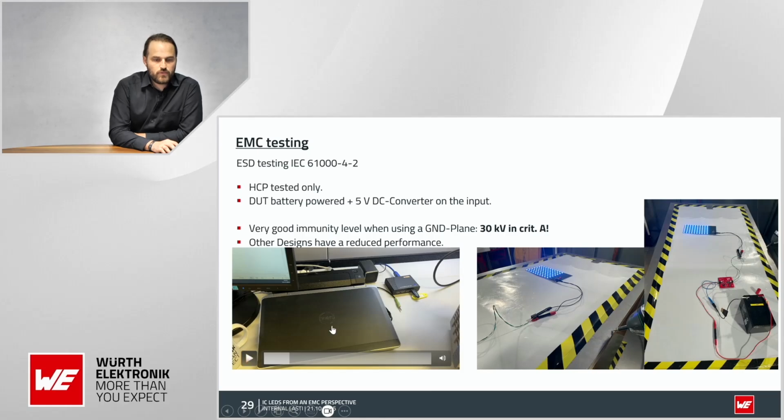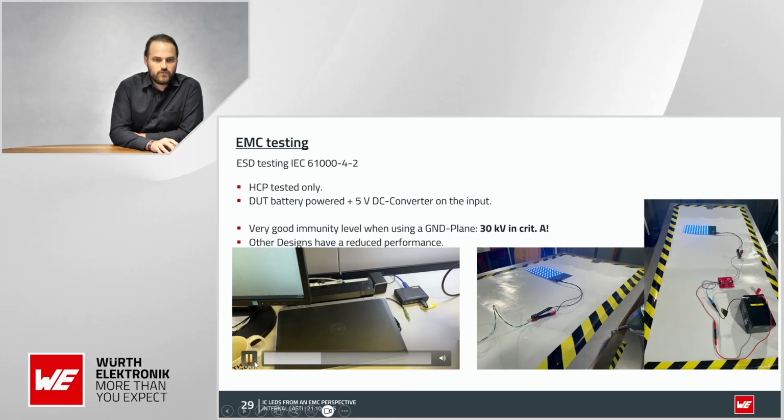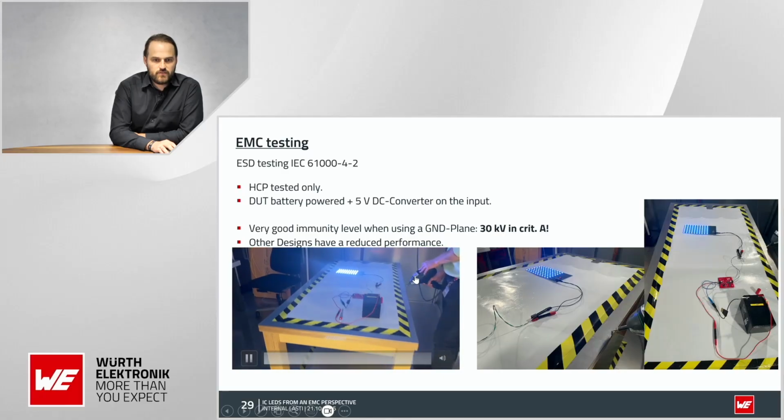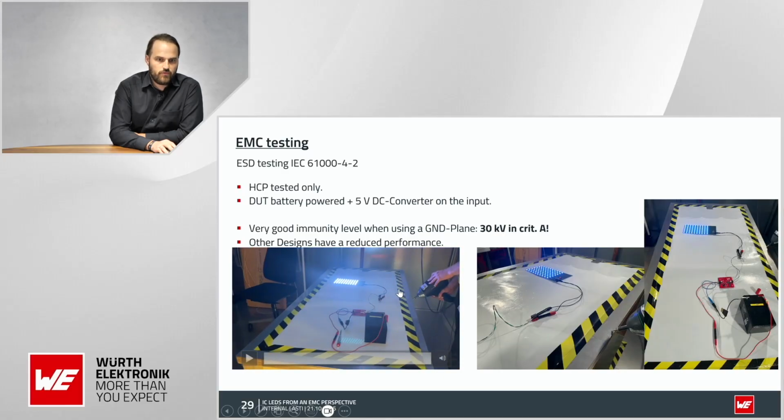This is the notebook that I'm using in front of the shielded room where we do transient testing. It is more or less used for doing burst and surge tests. And here you can see a USB hub, and this USB hub is disturbed by the ESD gun inside the chamber. You can hear how the USB hub is connecting and reconnecting, and here the colleague is using the ESD generator with 30 kilovolts.